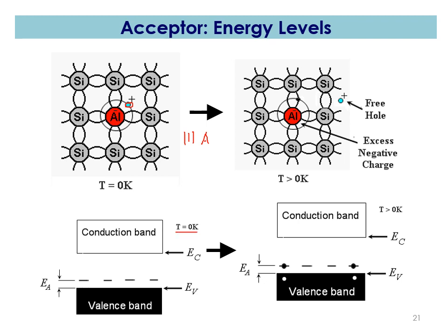At T equals 0 Kelvin, it will create the acceptor level in the empty space of the energy band gap, just slightly higher than the valence band, with a narrow gap, and the hole will reside in here.